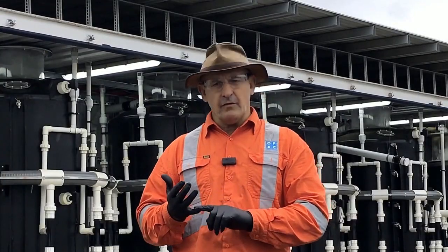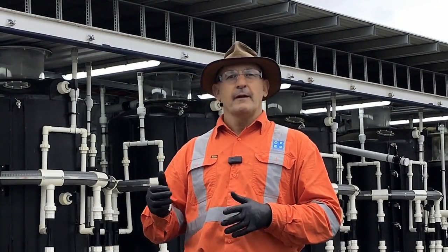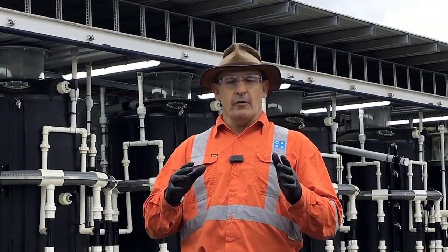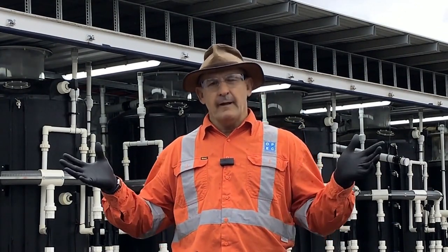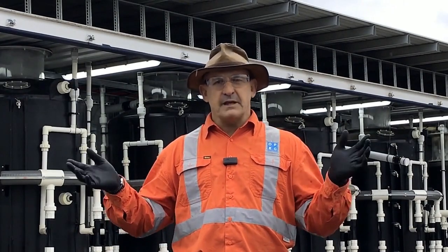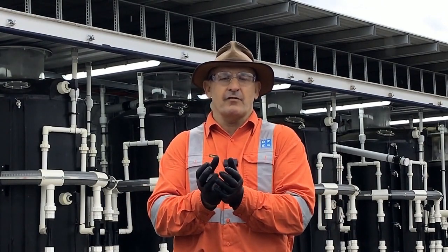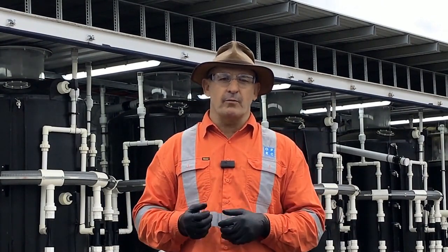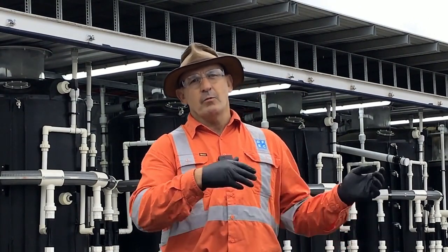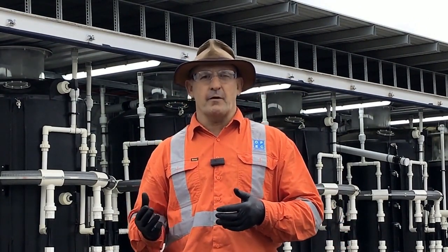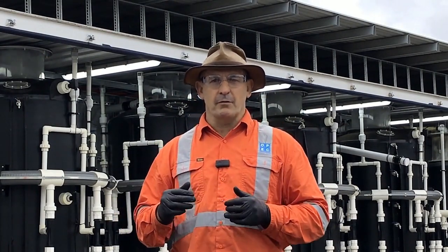So the issues of separation and concentration are undertaken in a single step using 3 different stages of fractionation that allows us to take large volumes of water that are contaminated by potentially low or average levels of PFAS and condense that PFAS contamination down into incredibly small volumes. So not only does the issue of what consumable use go away, we've also solved the issue of waste to a very large extent. We would argue that this is a primary lifter in any PFAS treatment train.